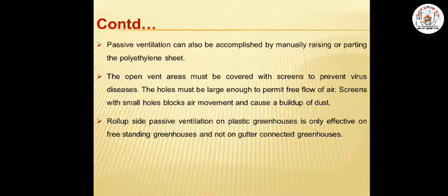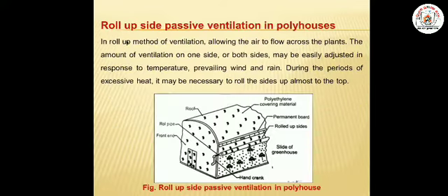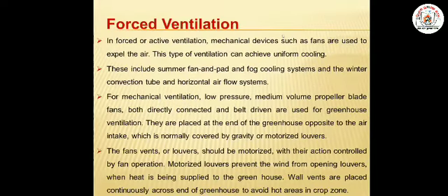Roll-up side passive ventilation on plastic greenhouses is only effective on the freestanding greenhouses, not on gutter-connected greenhouses. Okay, so in short, we have seen such a roll-up side passive ventilation system in the polyhouses. Okay, then next to that is the forced ventilation system.